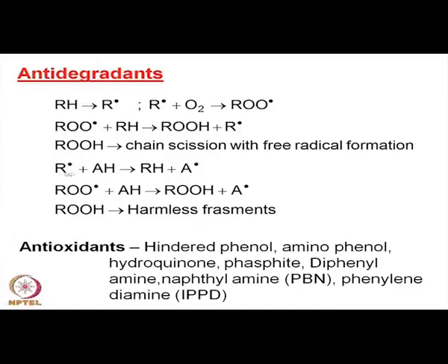So, even if some free radical is created, this antioxidant will revert it back to rubber hydrocarbon, creating a new radical. This radical is harmless, because the structure of these compounds is such that the electronic configuration of this radical stabilizes the free radical. This stabilized free radical is not as reactive as R dot, RO dot or ROH, etc. So, this is harmless.